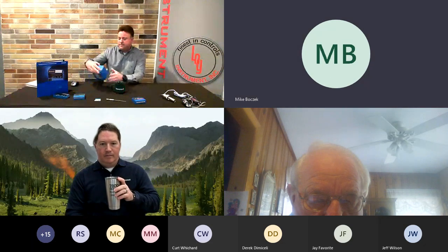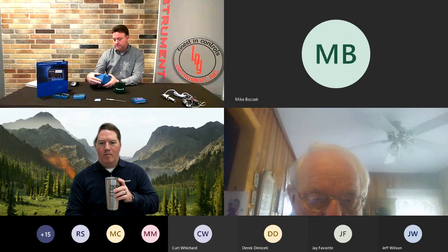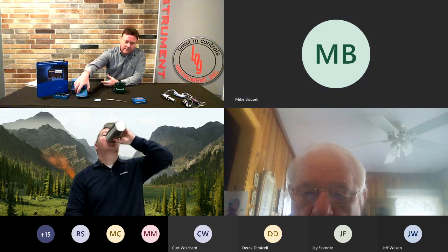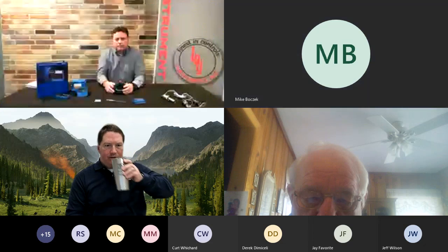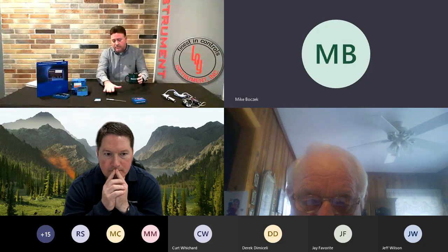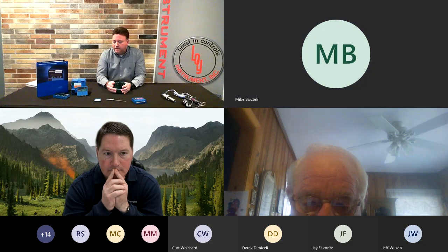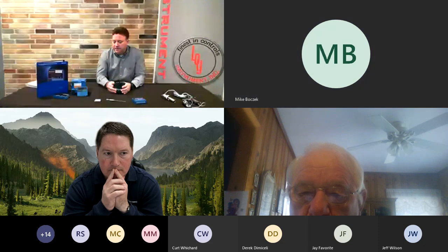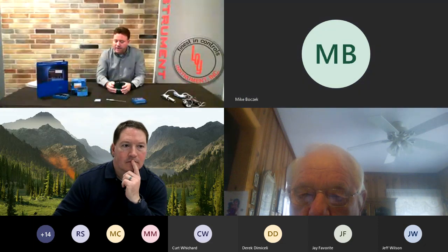Yeah, you can, I've done it, but you actually have to change the amplifier as well. Oh, okay. It's good to know. In most applications, like FM, NFPA, IRI, depending on the burner size, they might not allow you to recycle on flame loss. Right. There's not so many out there that we do that. Yeah, you're probably going to want to check that as well. Okay. Yeah, so it's important there to choose the right one.